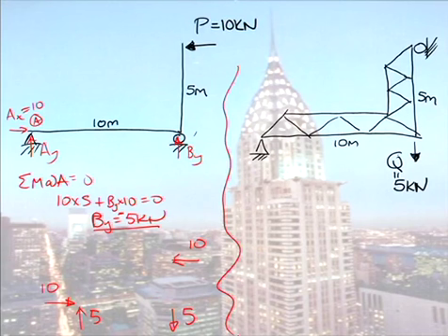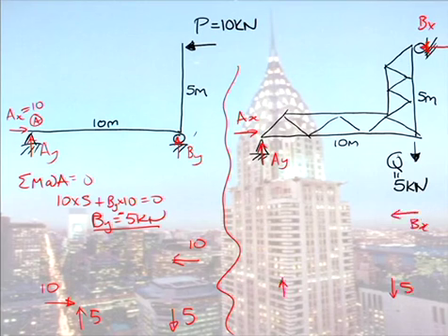Now, to the right, I have a truss structure. It has a pin support and it has a roller support. And it has a load, a vertical load of 5 kilonewton applied. Now, if I just draw that system of forces here, I'll call this AY again, and AX, and I'll call this BX. So if I draw that system of forces here, I have a 5, I have an unknown BX, I have a 5 up here, I have an AY up, and I have drawn my AX to the left here.